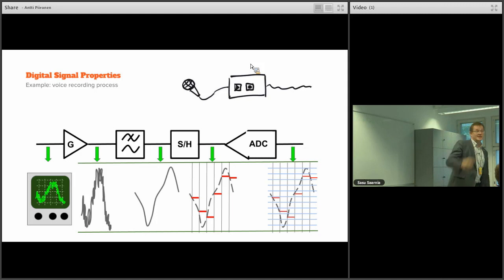Okay, it really does not show up, or is it the next one? Oh, okay. So these long blue lines are the quantization levels of the A to D converter. That's our whole A to D conversion range, and the distance between two blue lines means the least significant bit change.